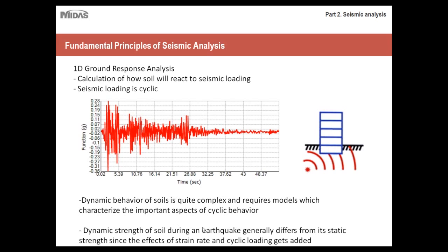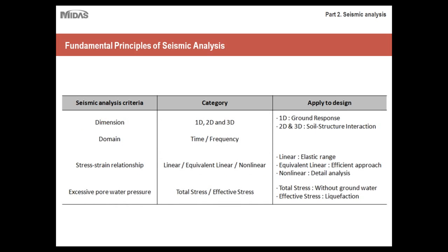And the dynamic strength of soil during an earthquake generally differs from its static strength, since the effects of strain rate and cyclic loading get added as well. So just keep in mind that the way a soil reacts to seismic loading is very unique, and static and typical live loads wouldn't be able to account for that.